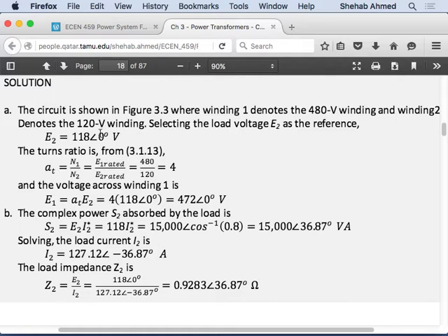We create one generator and say, this is my reference. I'm always interested in angle and voltage differences, but I make this reference have an angle of 0. That means all my other angles are actually absolute angles with respect to 0. That's the way we will go about doing things.